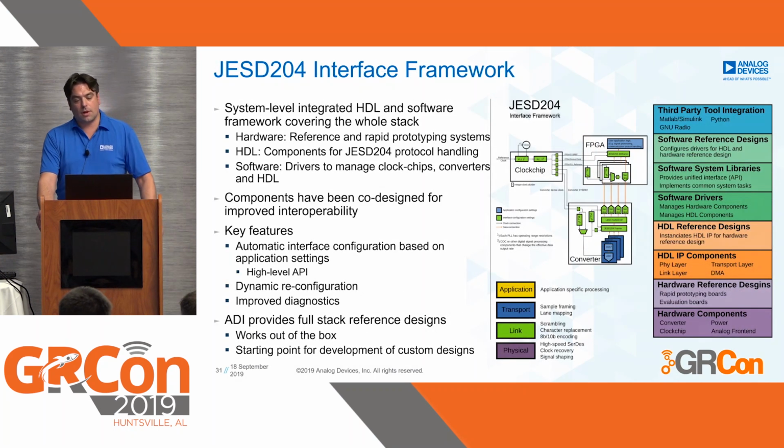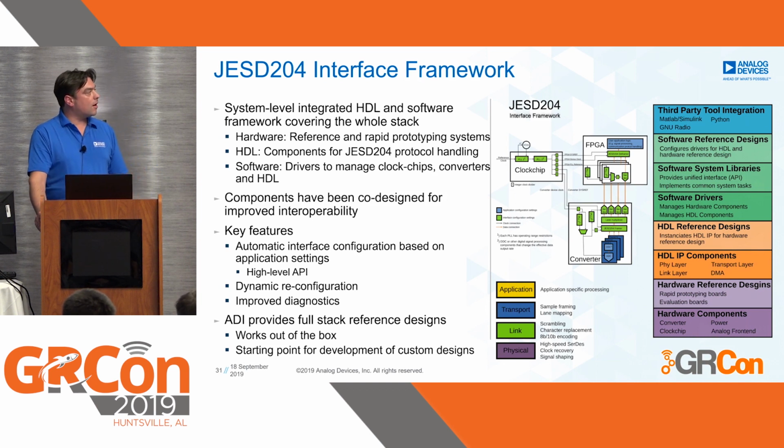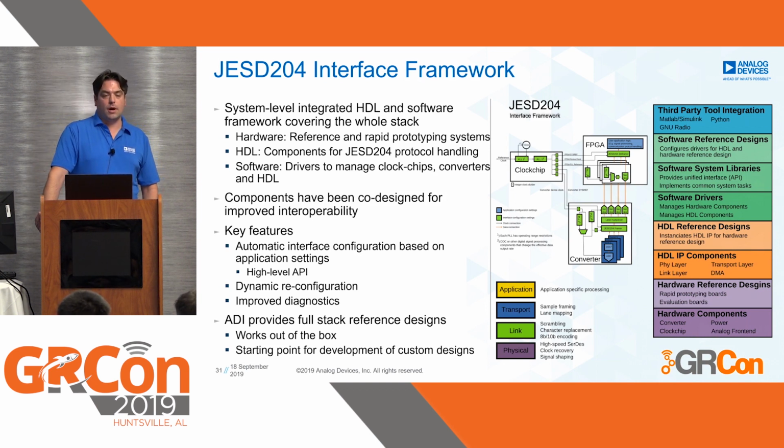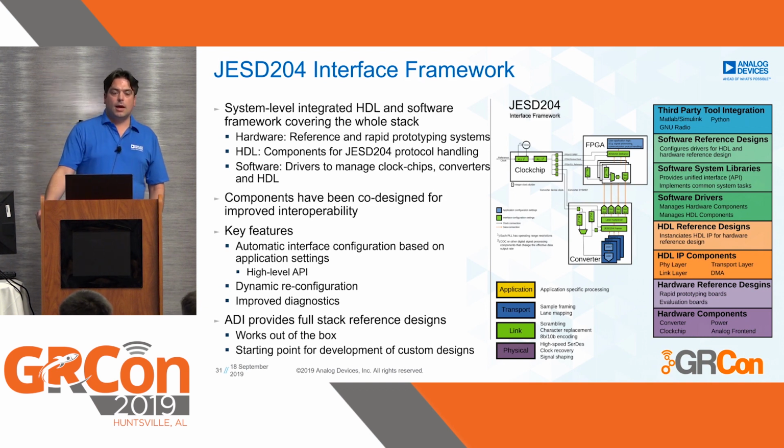A lot of people think JESD204 is complicated, and in theory it is a little bit complicated, but we have created this JESD interface framework, which makes it much, much simpler. It's an integrated software and hardware framework that covers the entire stack. We have generated HDL blocks for the link layer, and software drivers that configure the link layer, the physical layers, as well as the transport layers.